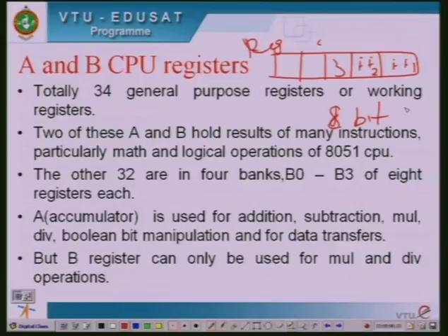Data can be stored parallelly or serially. If I call it a shift register, then I can shift in data from one side. For example, if I shift 1 into this, initially it had a 0, this 0 will go and sit in the next, and whatever was in this will go to the next. It is a shift register in that case. So then we can serially send in data. Otherwise, we can parallelly load data into all the flip-flops simultaneously. Whatever 8-bit data we have could be stored parallelly into each and every flip-flop, and this is what a register is. So this is what you studied.